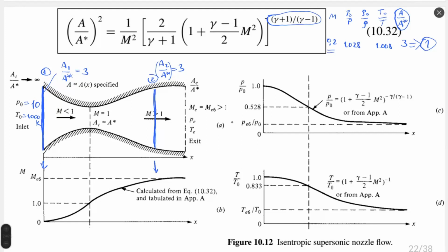Mach 0.2, pressure close to stagnation pressure, temperature close to stagnation temperature. Pay attention that these values are always bigger than 1 because stagnation pressure, temperature and density are the highest values in the system. So you cannot receive this ratio smaller than 1. This ratio must be equal to 1, which corresponds to Mach 0 when flow is not moving. When flow is moving, this ratio will be always bigger than 1.